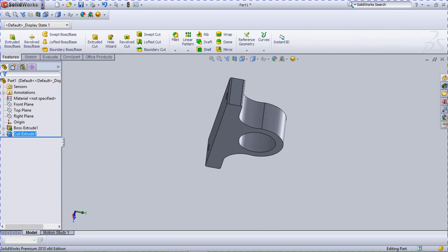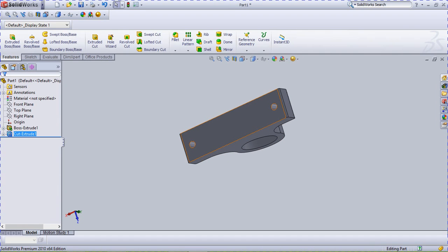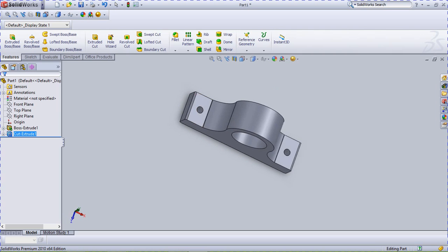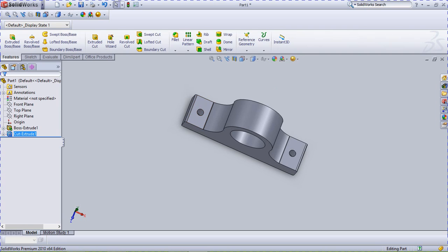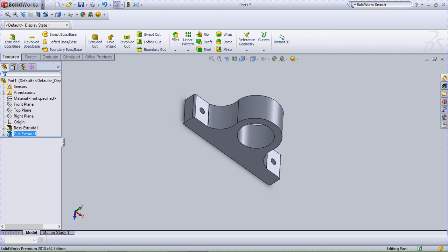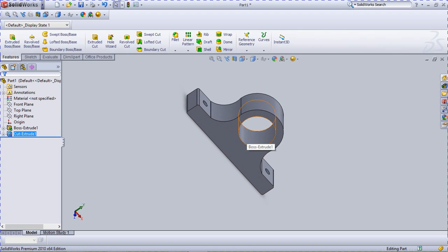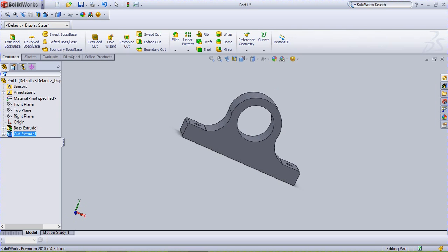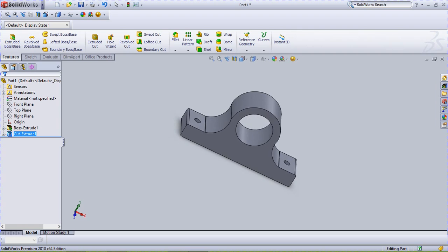See how it is. This is the face. This face should be a ground face or a scraped face. That should hold it perfectly in place. On the base plate you can give a groove to fix this bearing block so it does not move, in a micron-level way. Here you can insert a bearing, used as an interference fit, and then you can insert a shaft. You can run your shaft. Yeah, absolutely run your shaft.